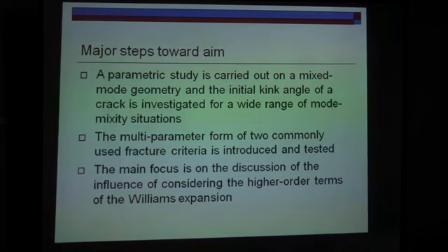Therefore, there are three major steps toward our aim. We did the parametric study, which was carried out on mixed mode geometry, and then the initial angle of the crack is investigated for a wide range of mode mixing situations.